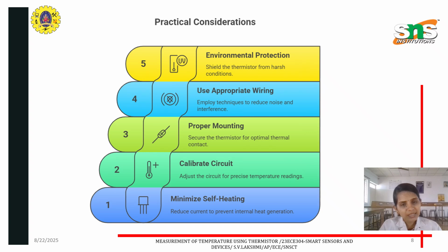So the practical considerations, as we have discussed, we can minimize the self-heating, we can calibrate the circuit, proper mounting of the setup, appropriate wiring and the environmental protection could all help us for the proper efficient use of this thermistor.